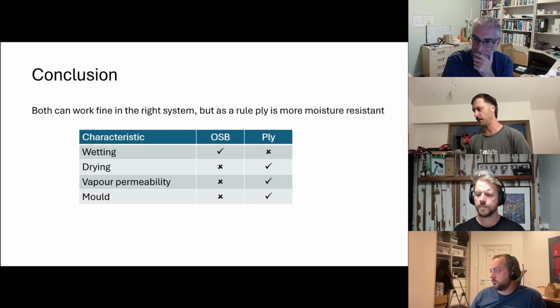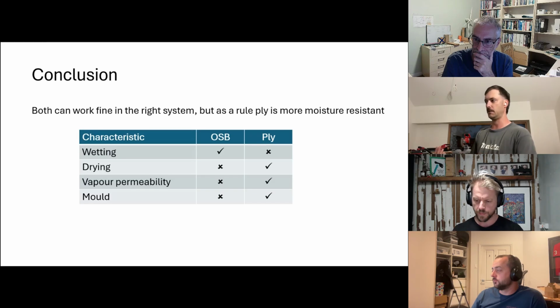But yeah, if it was, say, in Queensland or in the tropics, that's happening all the time. So that's when you're using something like a DA on the outside, an air barrier on the outside, and where solid sheathing is probably beneficial, but you really also want to have something that's not mould sensitive, because it's happening all the time. How did he go, Cam?